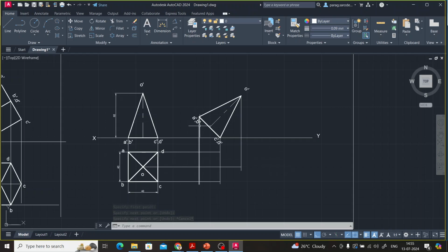Okay, now we name this. This is the projection obtained from A dash B dash. This is the projection obtained from AD. So this point should be A, so copy A. Similarly, on the same line, this is the projection obtained from CD and this is from AD. So D is a common point to both. Similarly, this is a projection obtained from AB and BC. So the common point is B. We are going to get it here.